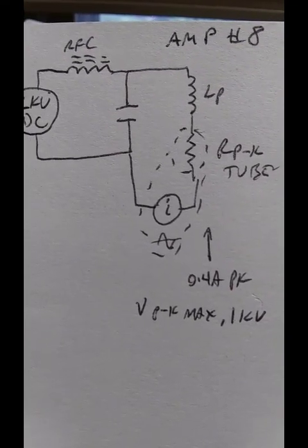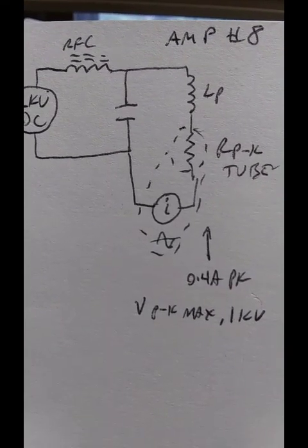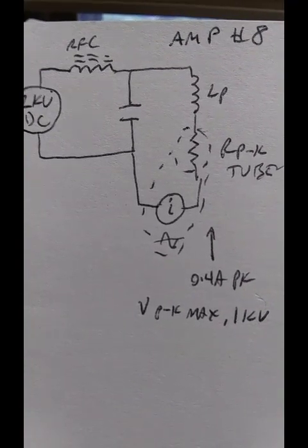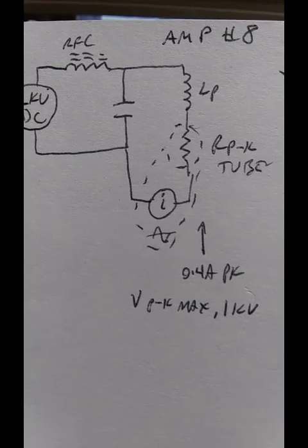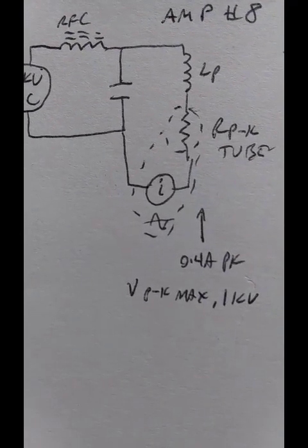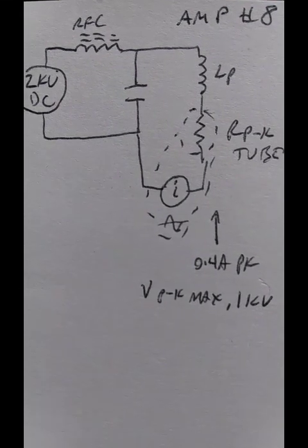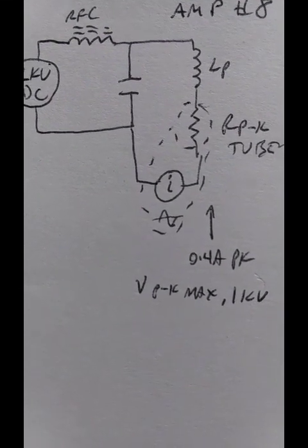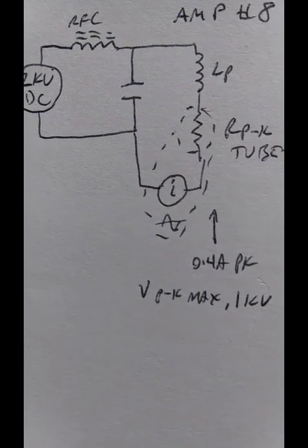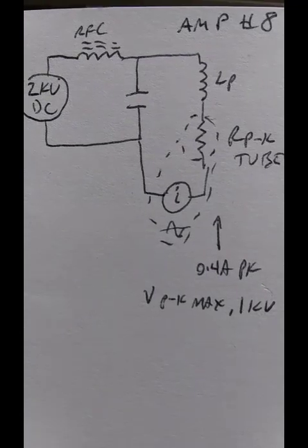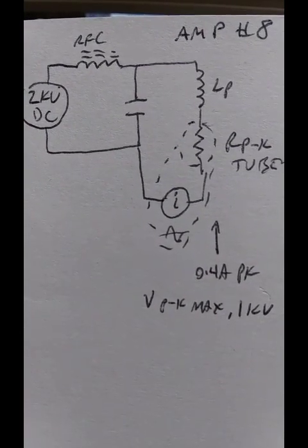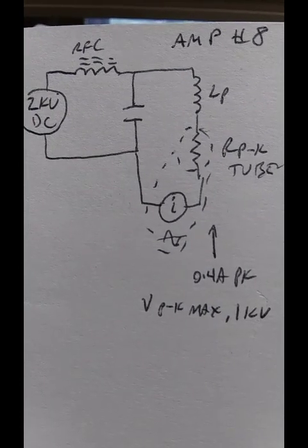Without being able to calculate it, we've got two options. Make it too low and burn the thing up. Make it too high and make the thing much too big and too expensive. And counterintuitively enough, a larger toroid core is not the answer. Larger cores have higher loss and will tend to burn up sooner than smaller. And the reason is, as an engineer from a toroid company told me, the smaller core has less permeability, takes more copper winding, so dissipation ends up being more in the copper than in the core. So completely backwards from what you might think.